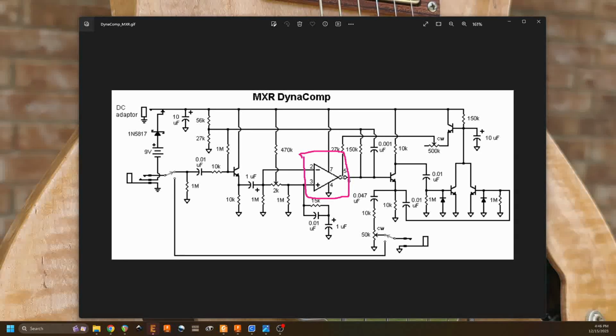But you'll notice that we've got these two circles here at the end that connect to a pin, which is a difference, but also the fundamental way that it works is different. So an op amp, or an operational amplifier, provides a voltage gain to a voltage input signal. However, an operational transconductance amplifier provides a current gain.